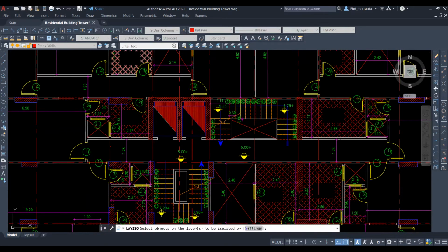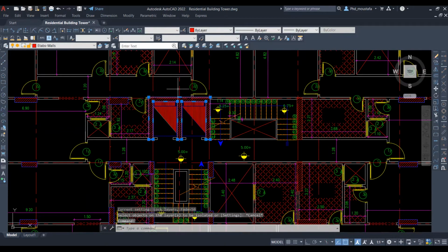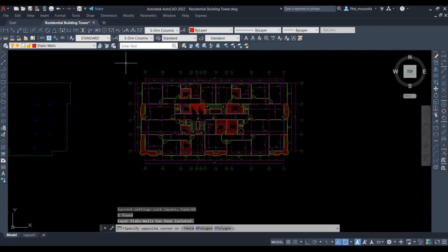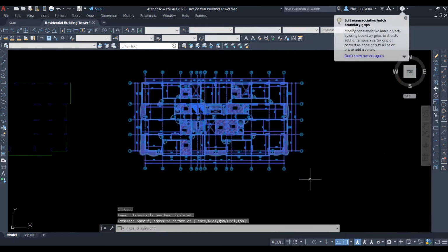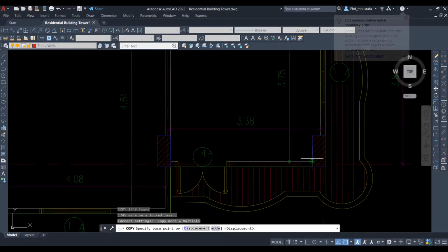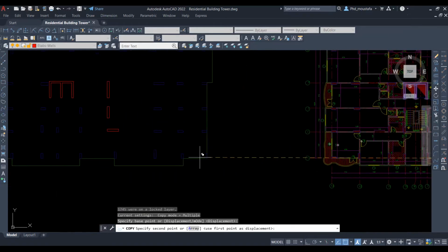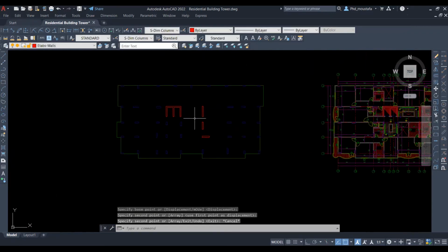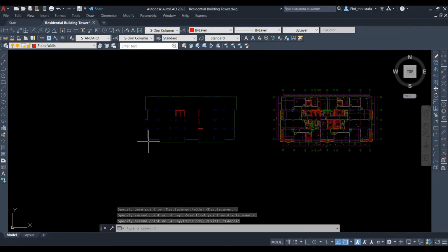Okay. Click on this, ETABS Wall, and press layer isolate. And then just select, Ctrl C or CO, and try to move from the edge so everything will be symmetric or overlapping together. Now we have seen the slab edge, which is the green one. We have the columns. We have a core wall here. We have 3 shear walls.